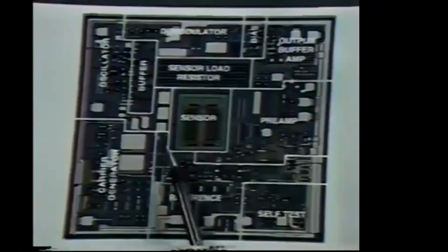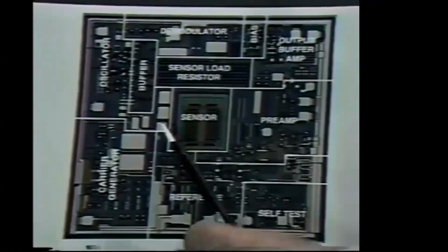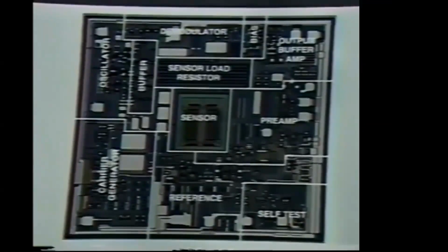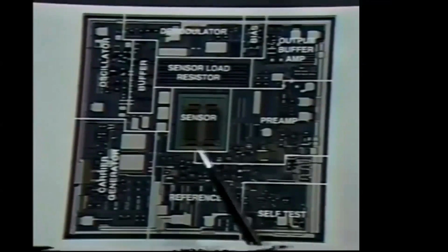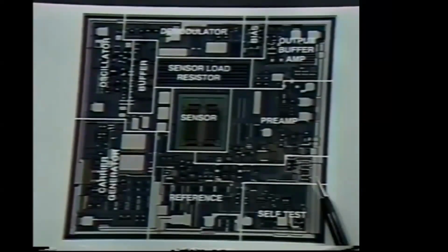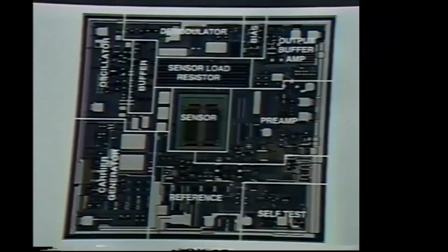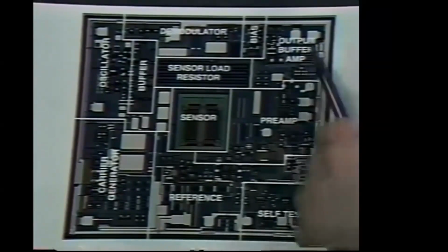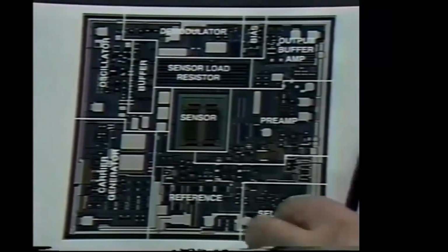So the improvements in terms of sensitivity and bandwidth were done mostly through improvements in the sensor. Some of you might have noticed that the original XL50 sensor was slightly offset from the center of the die. Symmetry is often wise in doing stress-sensitive devices, which just about every small sensor is. The device was placed in the center, and the electronics that was used is very much the same, with some minor changes. It's easier to see on the sensor itself the characteristic of some of those minor changes.